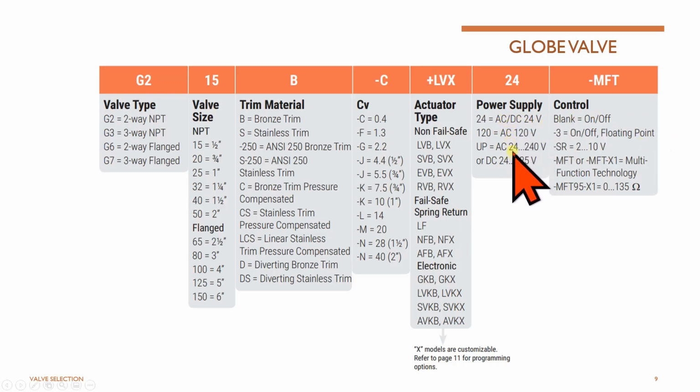What kind of power supply do you need? It depends on whether you're using 120 at your panel or feeding directly to the actuators, which your electrical subcontractor might provide. If they say they're not providing 120 at the actuators and will just provide 120 at your panel, then you can provide a transformer and use 24 from your transformer to the actuators. So based on all of that, you can select whatever you need.